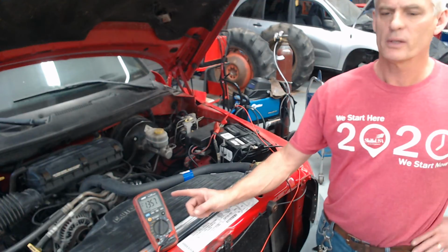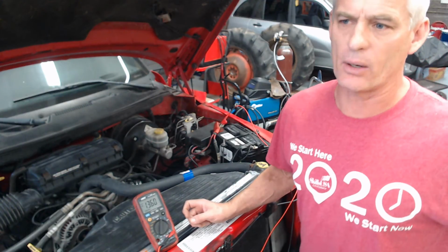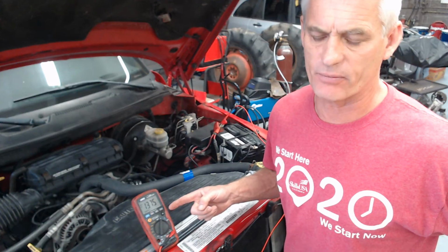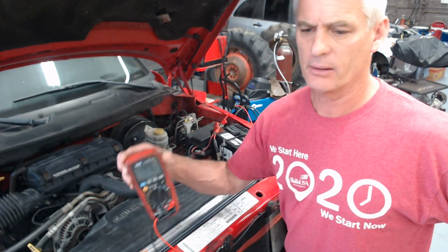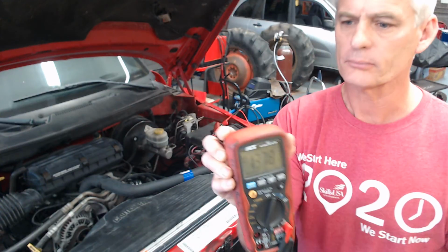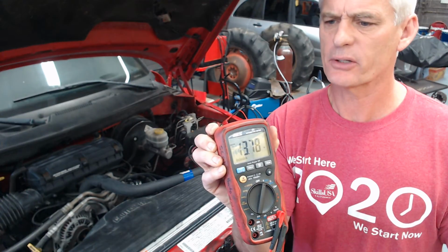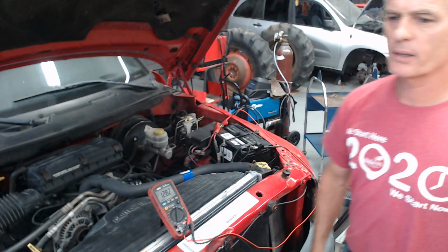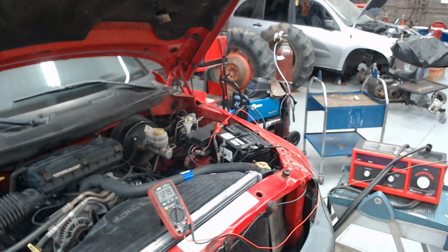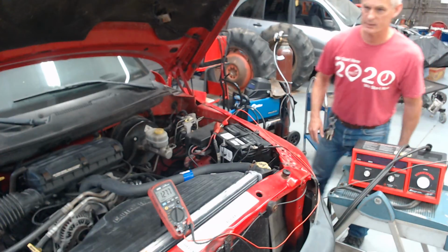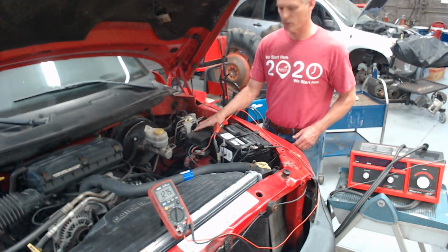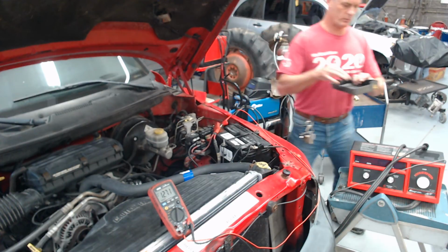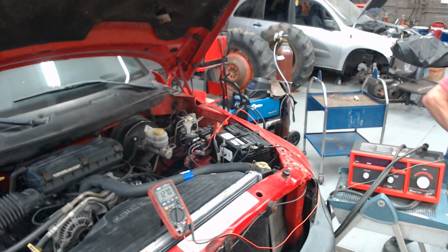So now, probably the digital readout was too much for you to see the cranking voltage, but there's our charging system voltage at approximately 13.78 volts. So what I'm going to do now is we're going to perform what's known as a starter current draw test. And in order to do a starter current draw test, once again, I do have to pull that fuel pump relay out so I can disable the vehicle from cranking.